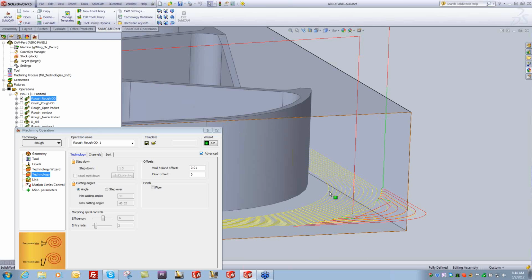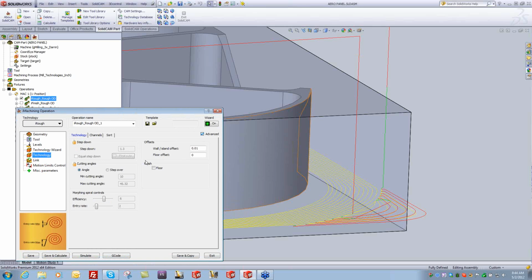Now, because of that, technically, with finishing, if you're only taking 10 thousandths on the floor, you're not worried about engagement. Just go ahead and cut. You can do a 75% step over. You don't have to worry about engagement. So yes, you could finish with iMachining, and maybe on a small floor it's no big deal. But if you're doing a lot of parts or something like that, I still recommend a traditional pocket for finishing the floors, which is why we'll never get rid of pocket or anything like that. We don't plan on getting rid of any of our toolpaths we've already created, but we do think that iMachining is probably, in 90% of the cases, the way that you should machine.